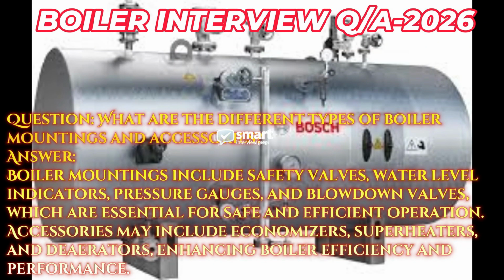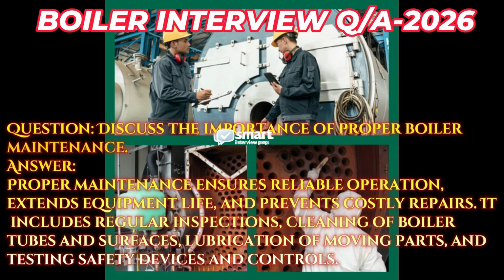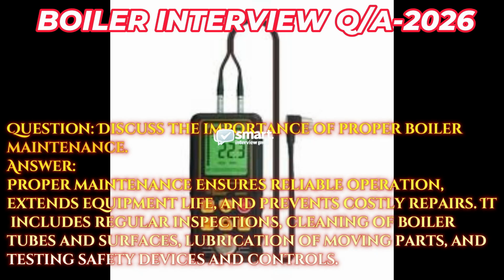Accessories may include economizers, superheaters, and deaerators, enhancing boiler efficiency and performance. Question: discuss the importance of proper boiler maintenance. Answer: proper maintenance ensures reliable operation, extends equipment life, and prevents costly repairs. It includes regular inspections, cleaning of boiler tubes and surfaces, lubrication of moving parts, and testing safety devices and controls.